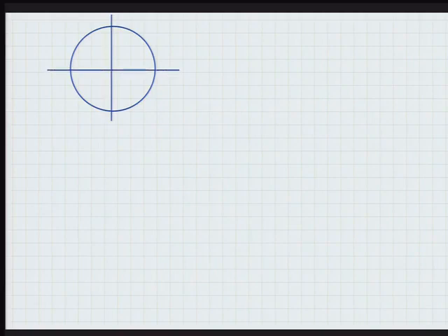If you want to fully eliminate the lowest frequency, omega equal to 0, DC, where would you put your 0? I heard the answer, but I want it louder. 1. Because at that point, omega is equal to 0, your distance to the 0 will be 0, so the frequency response will start at 0.